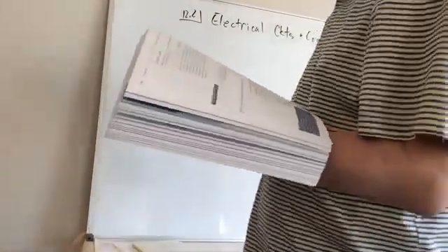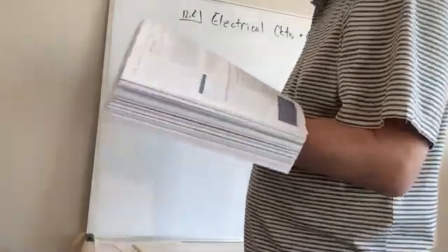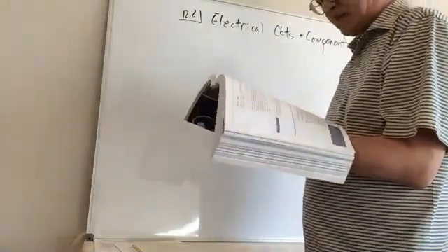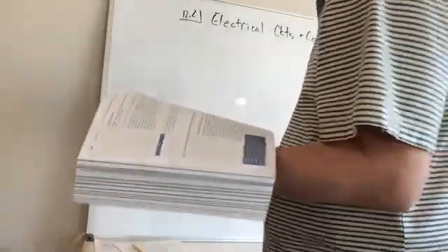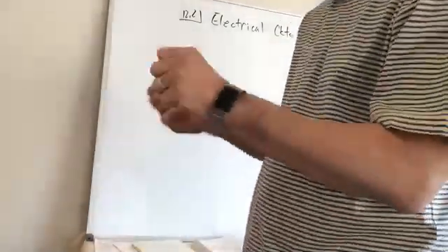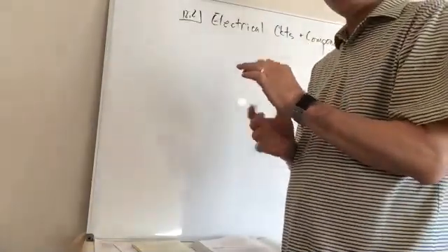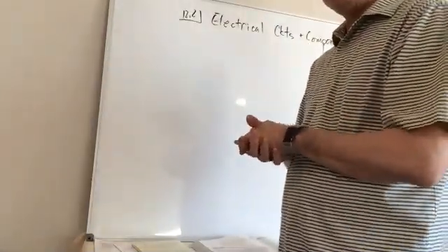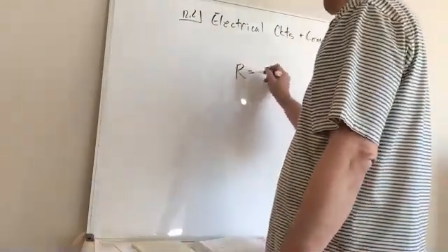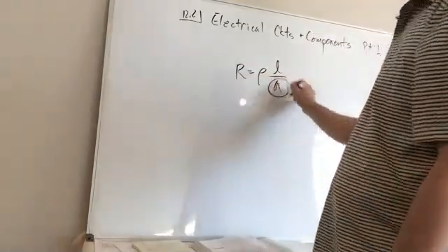As the wire gauge number goes up, do you think it would have more resistance or less resistance? You would have more resistance, right? Because you're trying to shove the current through a smaller cross section. The larger the cross section, remember we had the resistance was equal to the resistivity, the larger the cross section here, right?